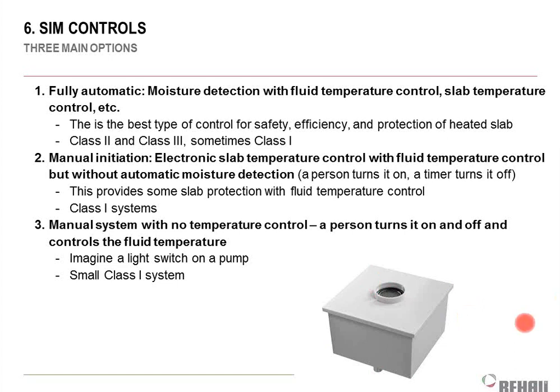So you put this outside, obviously, and there's a little electric grid. I don't know if you can see it through the webinar or not, but there's a little electric grid on top of this guy. And if there's moisture on there, meaning snow or water that lands on there, that moisture completes the electrical circuit between those various lines on there. And if we complete that electrical circuit, that closes a relay that says, boom, it's moist outside, right? I have water or snow on me. So he says it's moist outside, so it means I got water or snow.